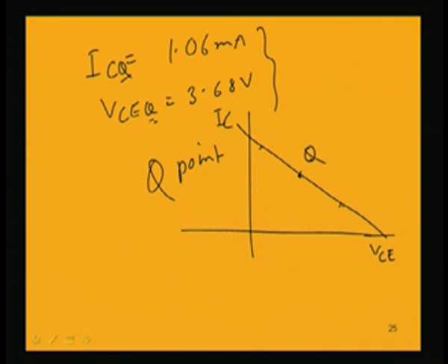In this whole discussion we have now discussed different biasing schemes. We have seen the potential divider biasing scheme has more flexibility, as well as being insensitive to beta as long as we maintain a particular design condition with respect to the resistances connected. Till that limiting condition is satisfied, we can make the operating point insensitive to change in beta.